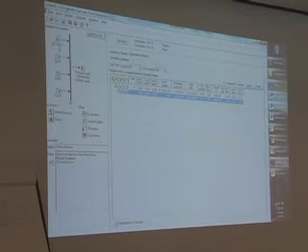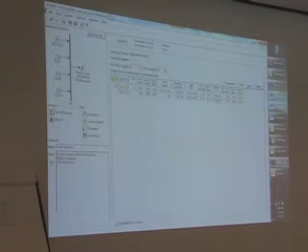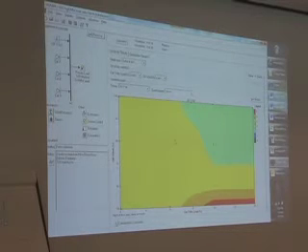This is actually not a very recent analysis, but it was just an easy one I could come up with that shows some really substantial fuel savings. Those 4 turbines bring you from 11.5 million liters down to 3 million liters a year. And that's without turning off the diesels at all. That's at that conservative operating reserve, 100% of the wind. So the wind doesn't allow you to reduce diesel runtime at all.